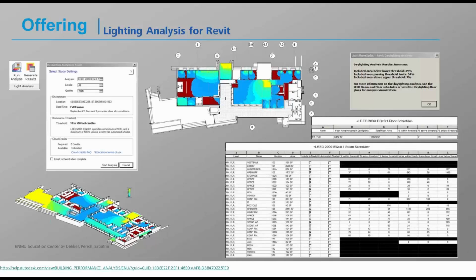Yeah, we have a lot of great questions on the line, David. Just to get us started, this plugin, is it localized? Can you use any climate zone or any weather station? Great question. I'll actually address this during the live demo, but the short answer is that it uses your Revit project location, which is a setting that you do in your Revit model, and it'll automatically look up the appropriate weather data and choose the appropriate day and time out of that data. So the process is automated as long as you set your location.